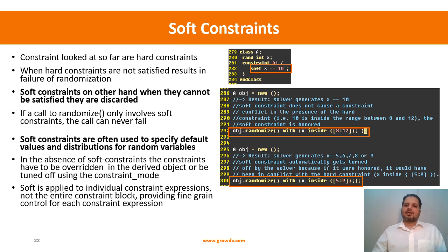So we have certain use cases wherein, let's say, I'm passing a specific value for a randomized variable from the command line. You know the command line, right? We run a test, and when we are running the test, I can pass a particular value, and I can extract that within the test using value plus arg, and then using the inline constraints.